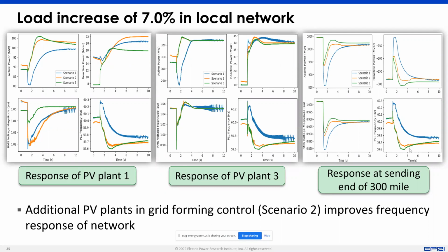In this, PV is providing. So the PV has headroom in it. It has both active power and reactive power headroom enabled in it. So it's not operating at maximum power point. So the PV inverter is providing grid forming. For this case, there was no additional battery energy storage implemented. So it's operating on the right side of the...